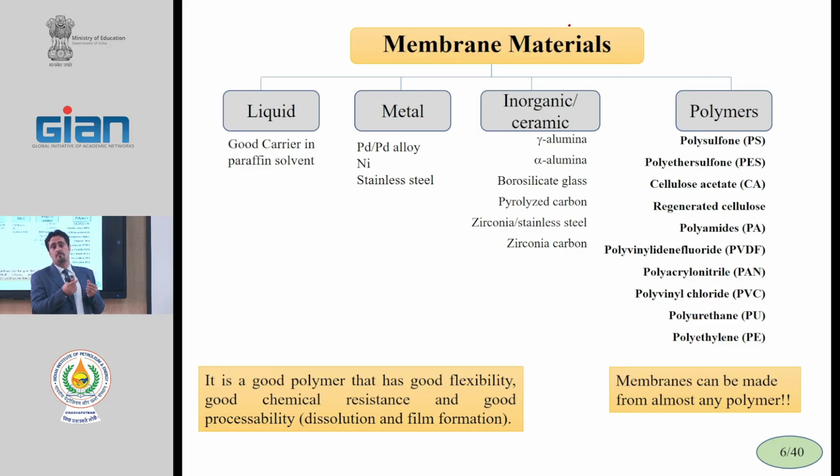We cannot use a brittle polymer in membrane fabrication, and we usually use amorphous polymers in membrane fabrication, amorphous, not crystalline. Crystalline polymers are brittle, and we cannot use them. And the molecular weight of the polymers should be high.